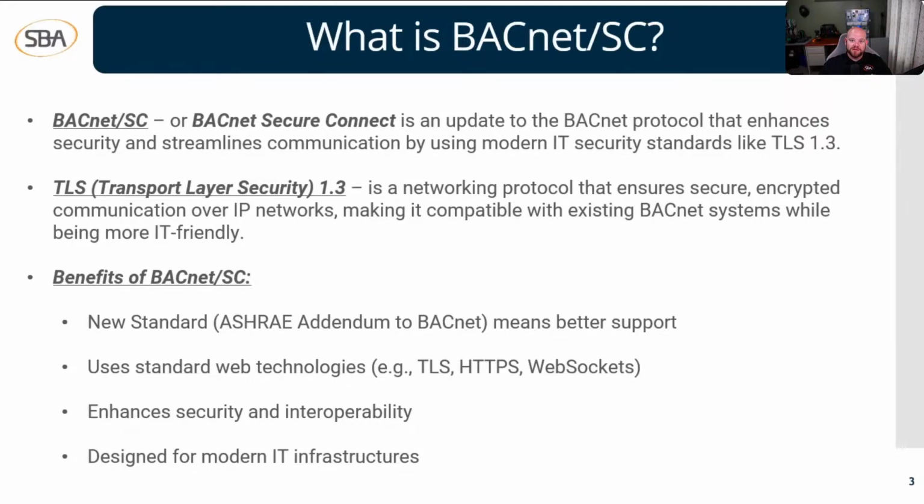If you're not familiar with TLS 1.3, TLS stands for Transport Layer Security, and TLS 1.3 is a networking protocol that ensures secure encrypted communication over IP networks, making it compatible with existing BACnet systems while being more IT friendly. So now that we know what it is, what are some benefits of BACnet Secure Connect?